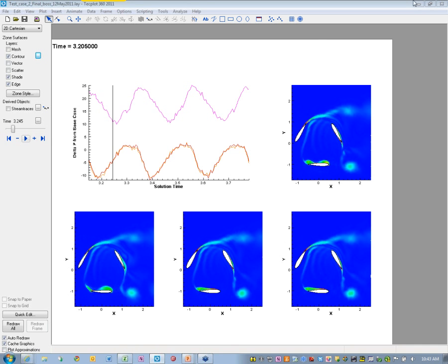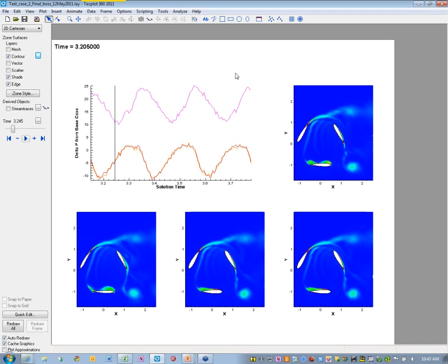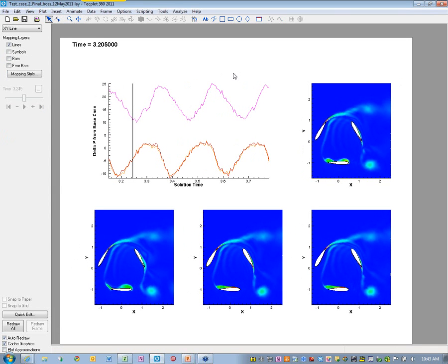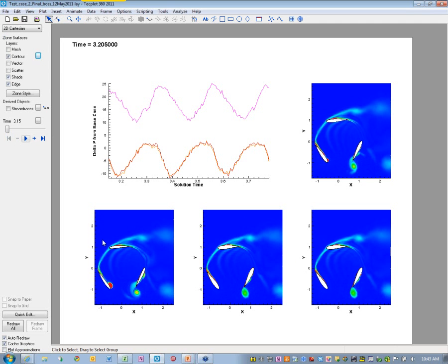What we're looking at here is the stages in the optimization. We have our initial design in the upper right station, and then we're walking towards the final design. All of these are linked together, and it's very easy to see. So there's that leading edge separation. If I hit play, Tecplot is going to go through and, again, be calculating. It's a fair amount of data, so it's computationally intensive, and I may not let it go through organically. I may just move the time slider to a couple of points of interest.